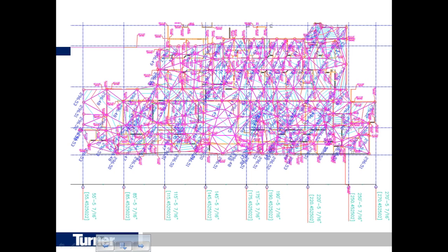The unique part about this topographical survey is that it shows an existing concrete slab. We had gotten the design from the architectural firm, and we systematically picked coordinates for doorways and medical equipment that had to be really precisely located, and got specific elevations for where the existing slab was in less than 12 man-hours.